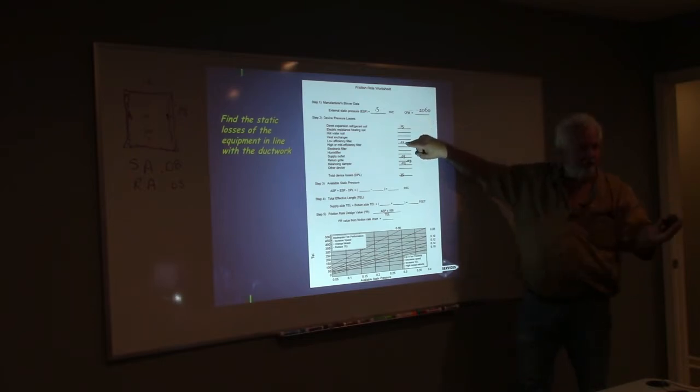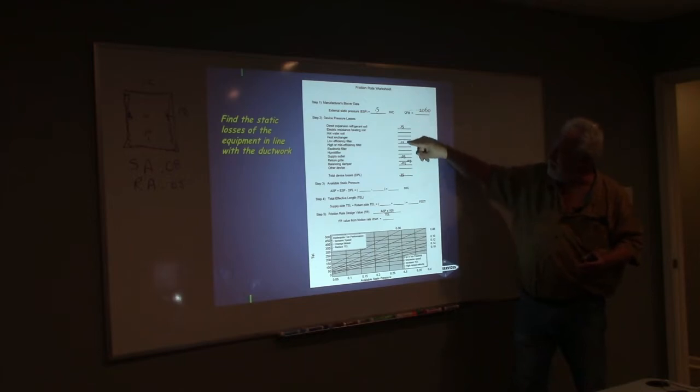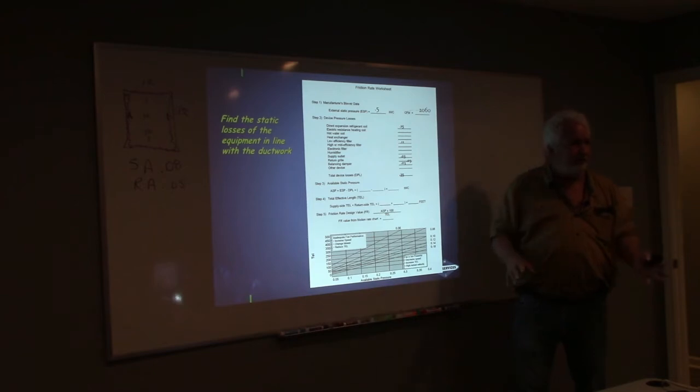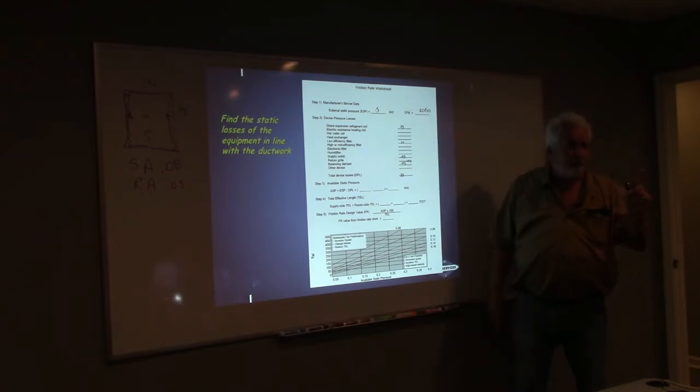Low efficiency filter, I went with the 0.11. That was that one that folded up. Supply outlet, that's that supply grill. That was that 0.03. The damper itself, 0.03. The return air grill, 0.03 on that one as well. It might have been 0.02. But I add these all up because these are the resistances that we just put in for that particular ugly duct run. That's 0.35. I have 0.5 total to work with, and this is what I have for the resistances on that system.